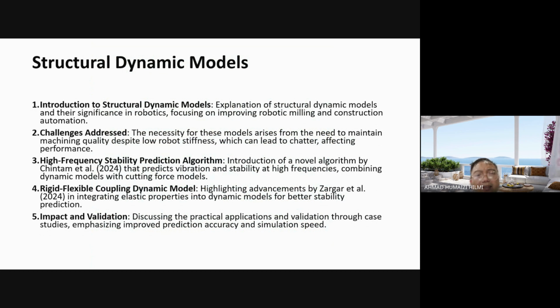They predict the vibration, and the algorithm, the model, will prevent that vibration from happening, so that the thin cantilever can operate in cutting. If not using this model, the thin cantilever will vibrate more, and the cutting quality is not that good. So this is called the structural dynamic model.